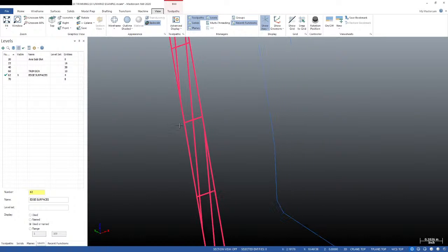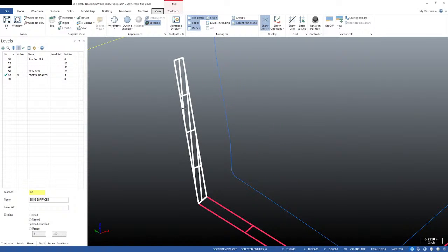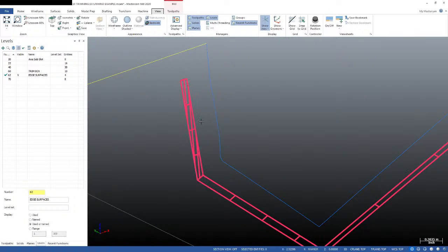If I zoom in on this surface over here, it's a nice flat surface, but look at the UV lines on the surface itself. These lines, column U or column V, in this case let's just call them U, these little horizontal lines run along the direction of the surface that is good for us. These other lines are at some weird angle that is not perpendicular, so the U and the V lines are not perpendicular on this particular surface.